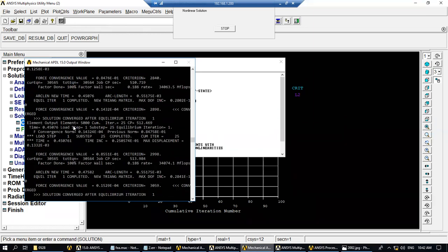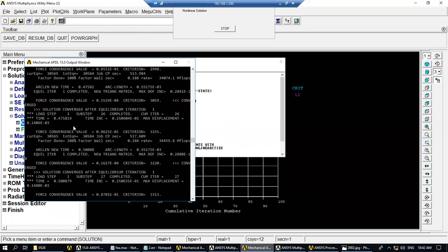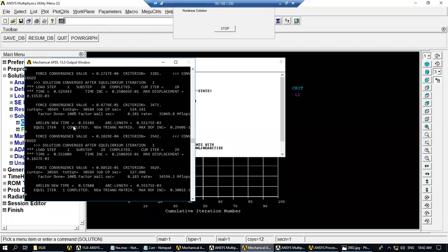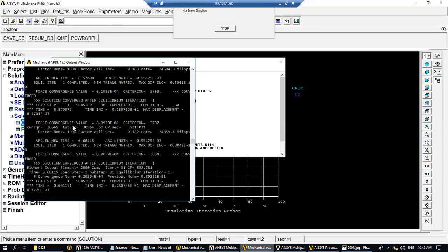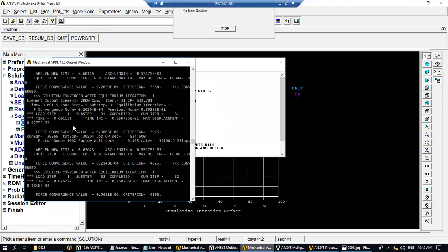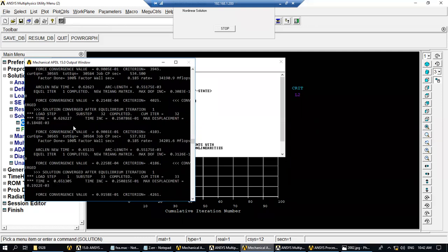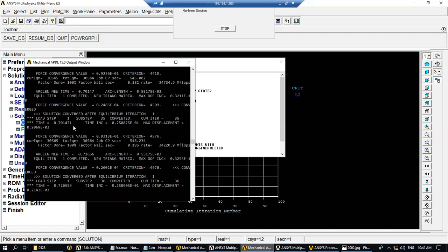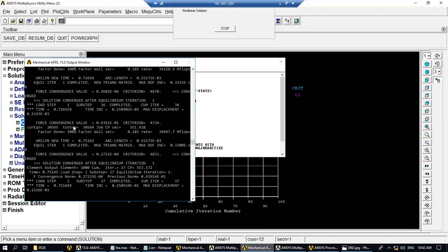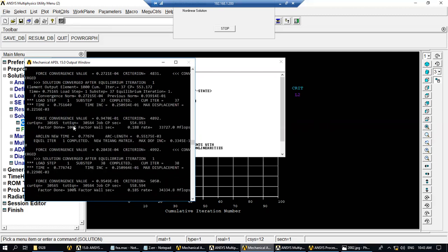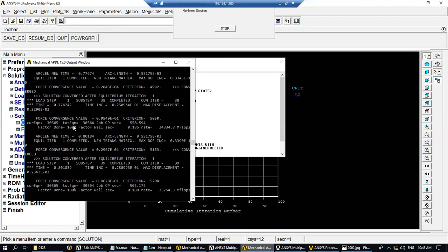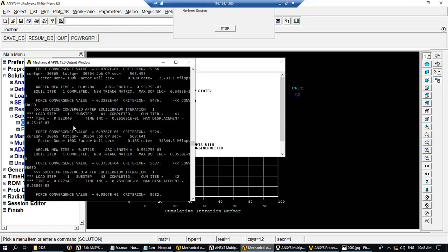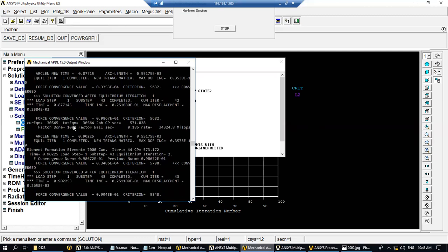And if you check, there will be deformation and there will be a stress, but the stress will be, of course, less than the yield stress of the material. So that's the idea. And basically, we have these two different types of analysis. They are both static analysis. But for this case, like what we are doing now, we have a certain load, like you can say from the environmental condition, the pipe or the structure is supposed to be subject to this kind of loading with a fixed number.